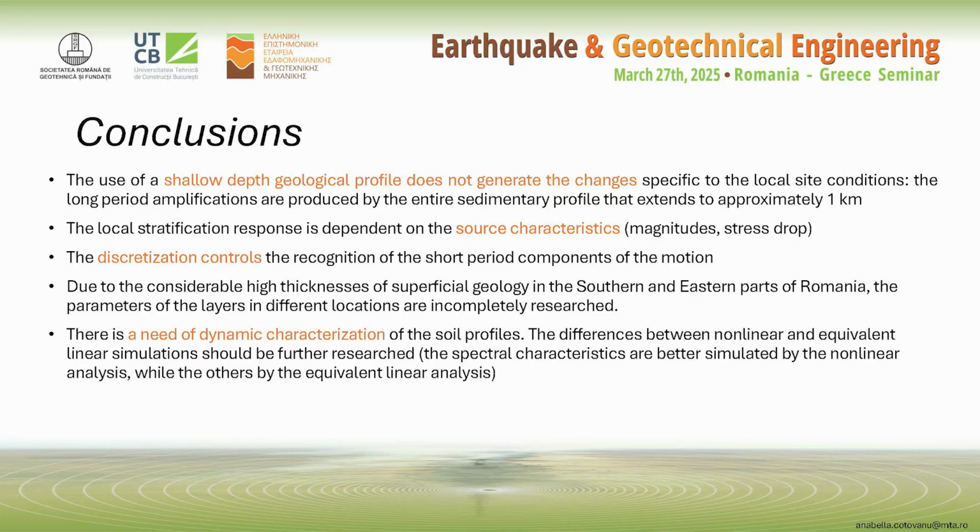So in conclusion, a shallow depth geological profile does not generate the changes that we recorded for the longer periods. So we need to use the entire sedimentary profile of more than 1 kilometer. The local stratification response is dependent on source characteristics, so we should not extrapolate from lower magnitudes to higher magnitudes. The discretization controls the short period components, and we need dynamic characterization because of this high thickness of superficial geology.